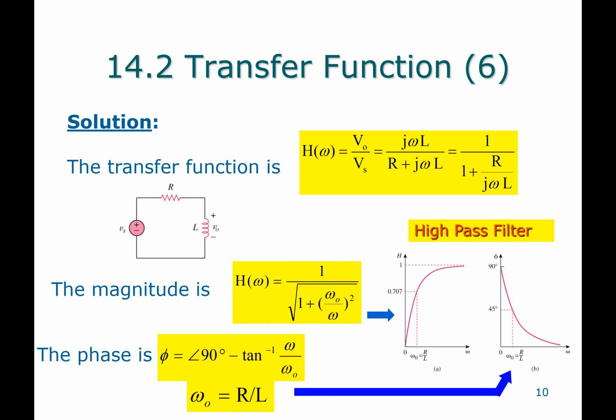And again, the transfer function looks like this now. It has a suppression effect when you're below omega 0, and it has an allowance effect that allows things to go when omega is above omega 0. This is the basis of filtering audio signals as well in your phone, in your stereo. Very useful. Comes up in so many circumstances.